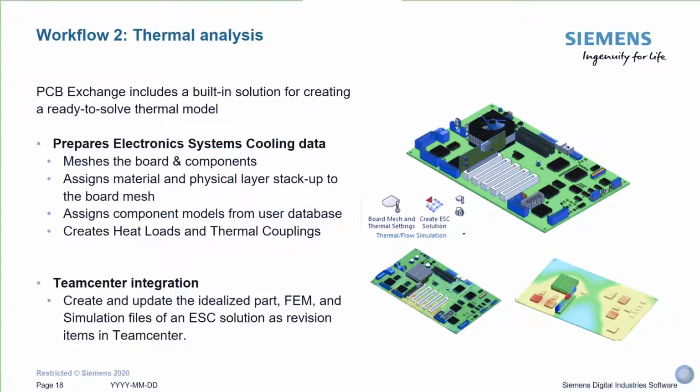So with PCB Exchange, you can automatically mesh the board, create your finite element model, create your simulation file, mesh the components, create the simulation objects, and all the different boundary conditions required for you to run your analysis.